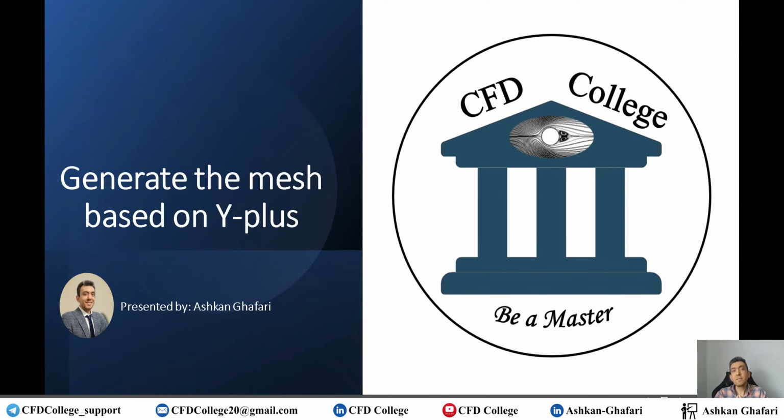And after that, we can modify the mesh if the y plus isn't in the range that we want. But it's good to generate the first mesh based on the y plus that we want. So in this video, I'm going to teach you how to do that in external flow using two Excel files and in ANSYS Meshing.